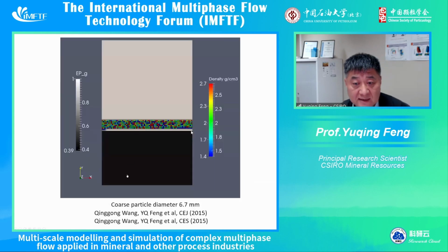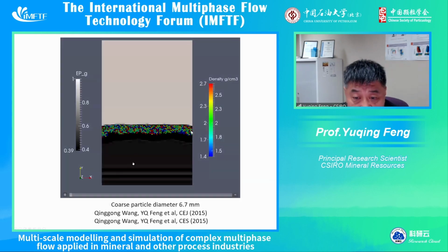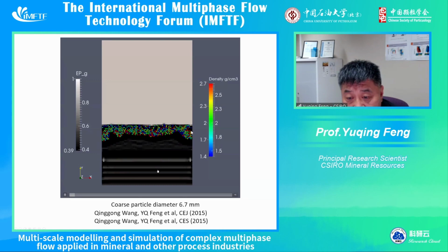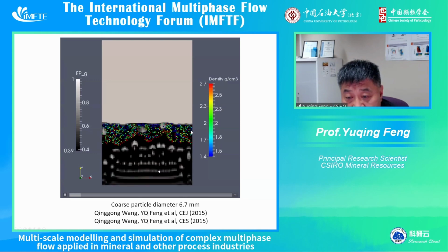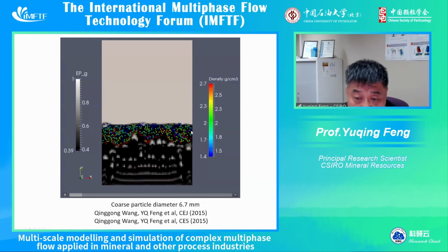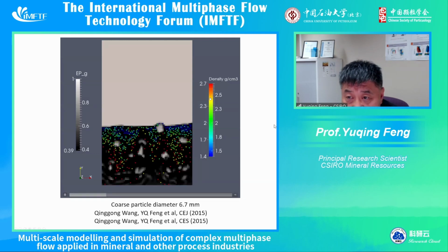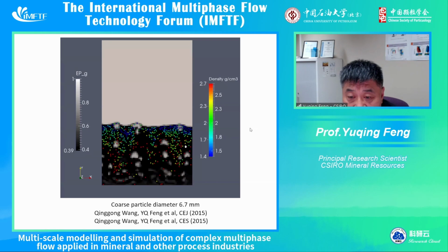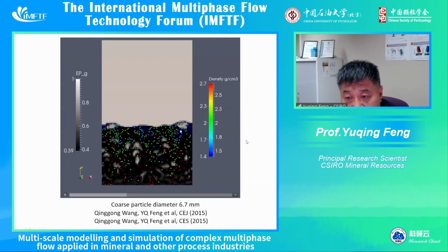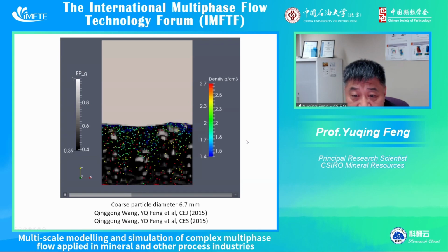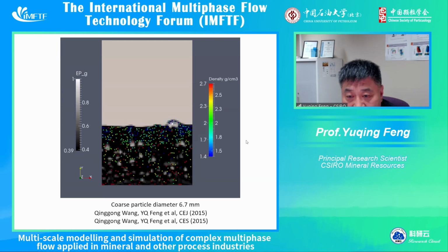Yeah, you see, for the fluidized bed media, the fine particles use the two-phase model approach or the regular method, and the large particles use DEM. Then the high density, heavy ones sink at the bottom. It's simply like floating over water. We call this dry separation, and the light ones are on the top.